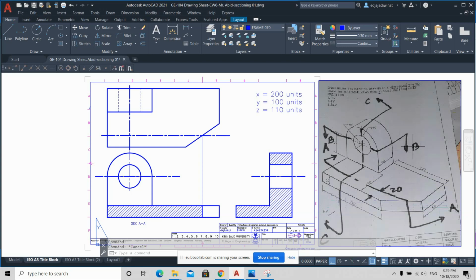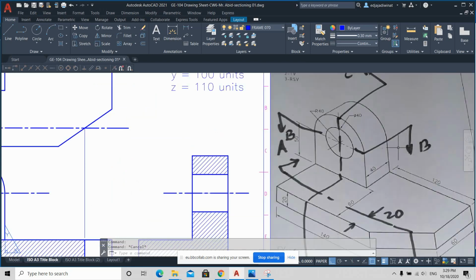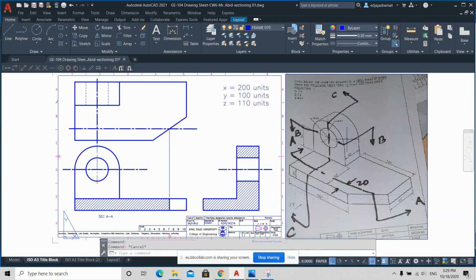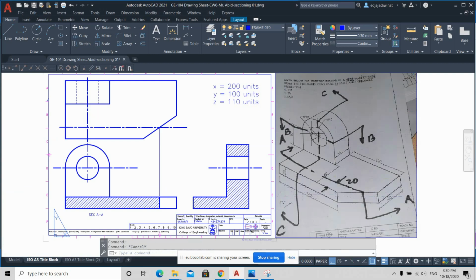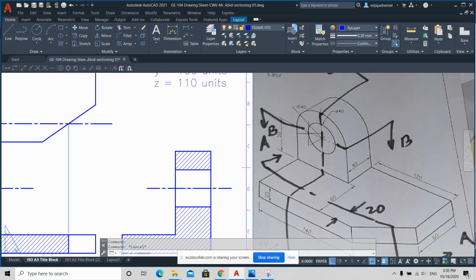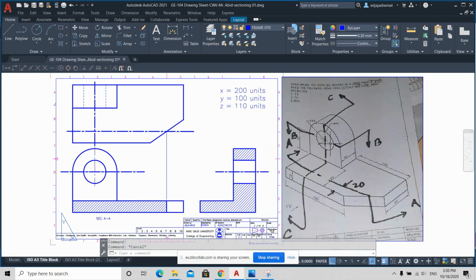All right. So try to imagine what will happen here. Let's go step by step. So you cut here. I will throw away the object behind the arrow. This will be gone, and you will keep the things below, or pointed to by the arrow. Then which region will be hatched? It will be this region and that region. While in the middle, it's just air, so you will not hatch that.